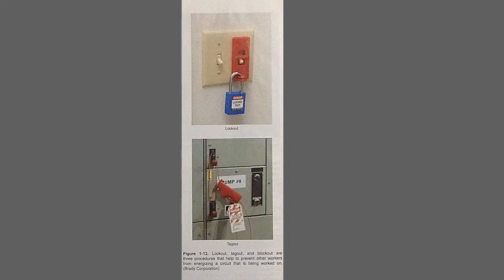Helping a shock victim. If a co-worker is a victim of electric shock, tell someone to call for help while you start to assist the victim. Immediate action must be taken to help a shock victim. This is particularly true if the victim is still in contact with the source of electric current. If you cannot shut off the power immediately, remove the source of electric shock without touching the conductor or the victim. Use great care that you do not receive a shock yourself. After all, you will not be able to help the victim if you yourself become one.